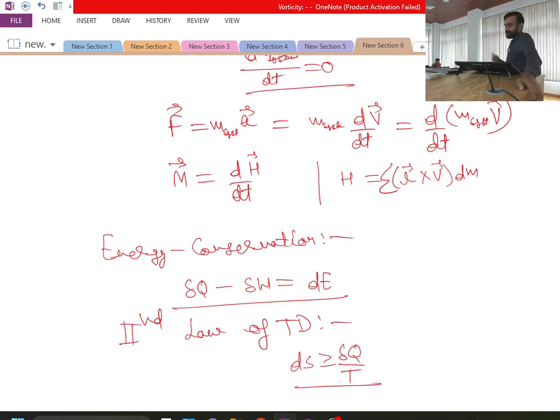So in fluid flow we majorly use the Eulerian approach, where we fix the control volume, our region of interest, and within that control volume we find the variations in flow parameters. While these variations take place, the identity of the fluid does not remain fixed; fluid keeps entering and going out.